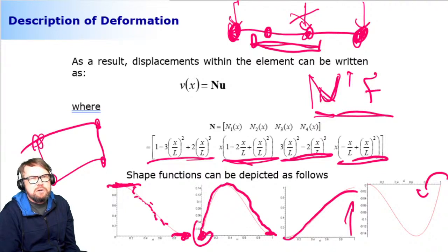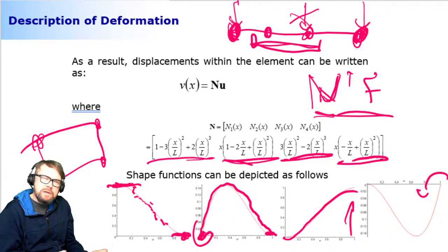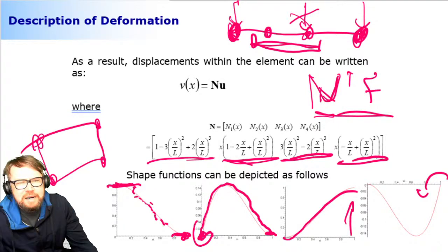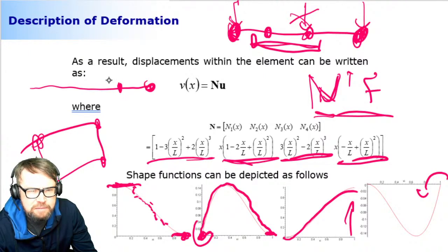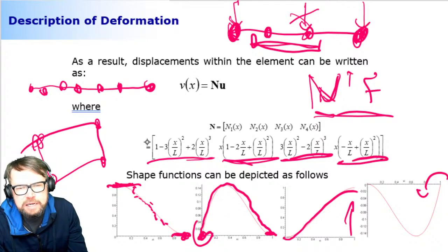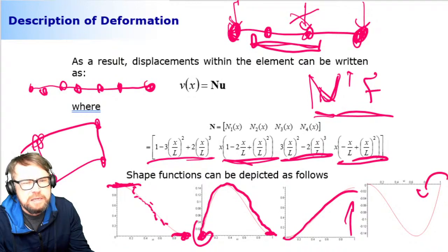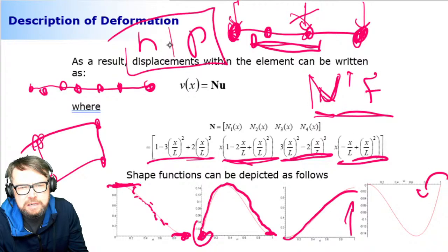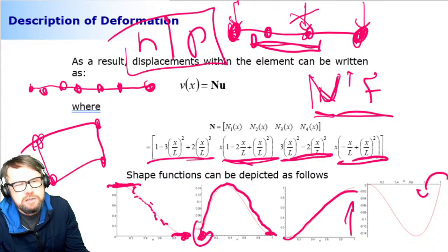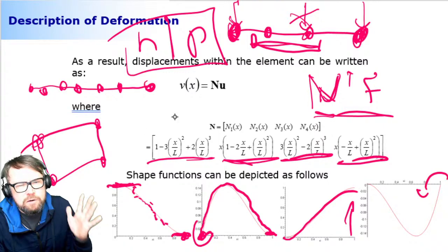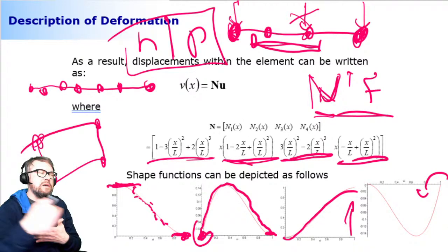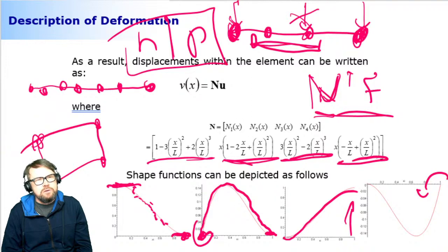But you can get this convergence also by increasing the number of elements. By the way, these are like 2 different finite element methods. I said that you can get a better solution by increasing the number of elements. Yes, that's one way to do it. Or you can increase the order of the polynomial within one element. Those are like h and p refinement, if you look at the finite element literature. So it's h and p refinement. They are either increasing the number of elements or increasing the order of polynomials. Both bring the same kind of consequence, which is a better solution.